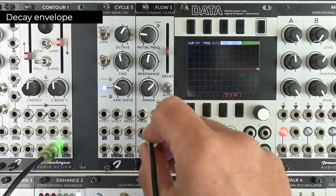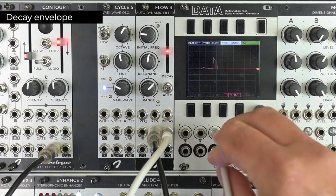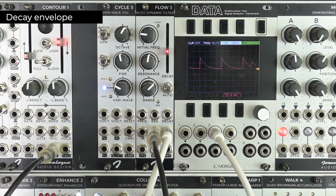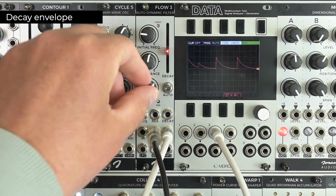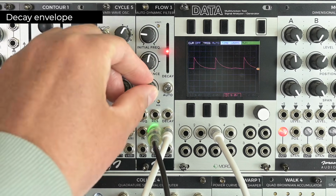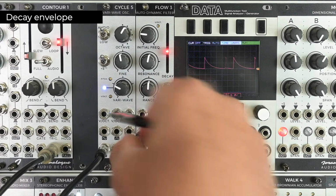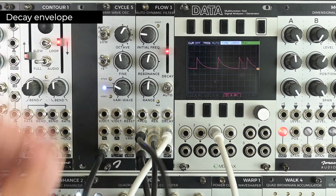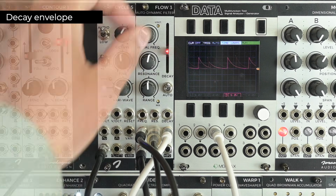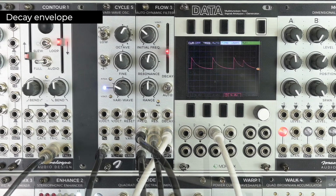By the way, when you connect the envelope output to something, you can just extract the envelope generated by Flow 3 separately from its functionality as a filter. And when I turn the range knob, you can see that the signal from the envelope output is not affected by its setting. So even when you're using Flow 3 as a filter, as long as you keep the range knob in the 0 position, you can still extract the decay envelope from the envelope output.